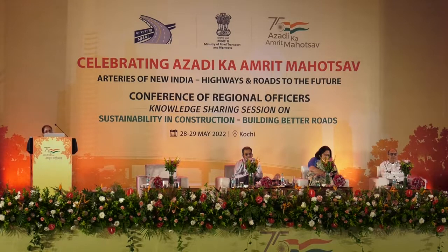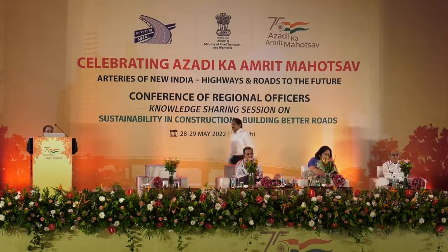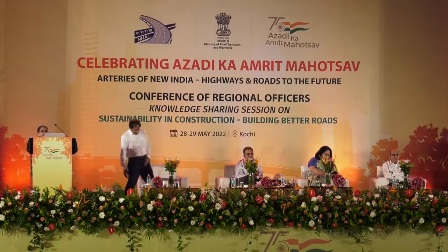Here again, when I come to innovation, BPCL has created a product called polymer modified bitumen plus. What we have done specifically is added 2 different polymers into it. Keeping 2 polymer systems in one solution is a challenge, but this product is not only taking care of very extra heavy loads, but also taking care of fuel spillage. So in areas where you have very high fuel spillage, there also you can use it.